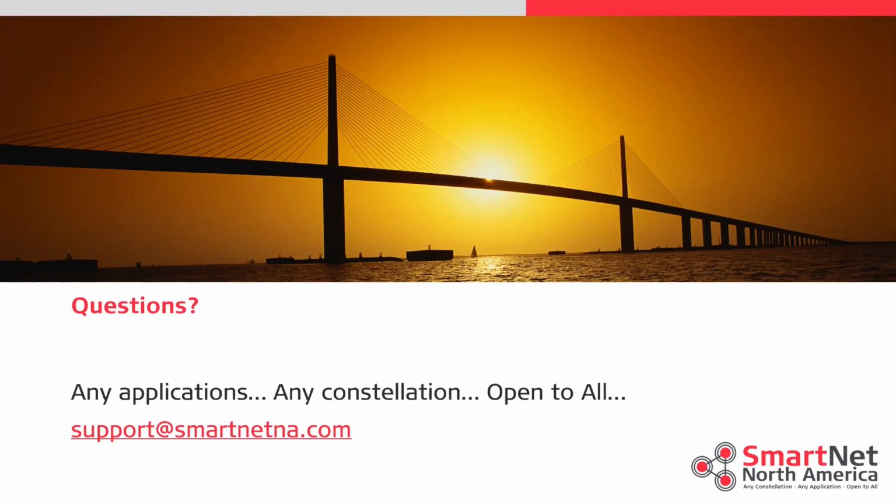So today, November 19th, we are broadcasting in the US an NAD83 CS1 solution, and in Canada a V6.0 solution, and that is what's being broadcast today. So if you're on the production mount, the standard RTCM3 iMAX mount point today, that is the coordinate that you are getting. On January 6th, you'll get a CS2 realization coordinate, or a V7.1 coordinate in Canada. So we'll broadcast different coordinates on that date.